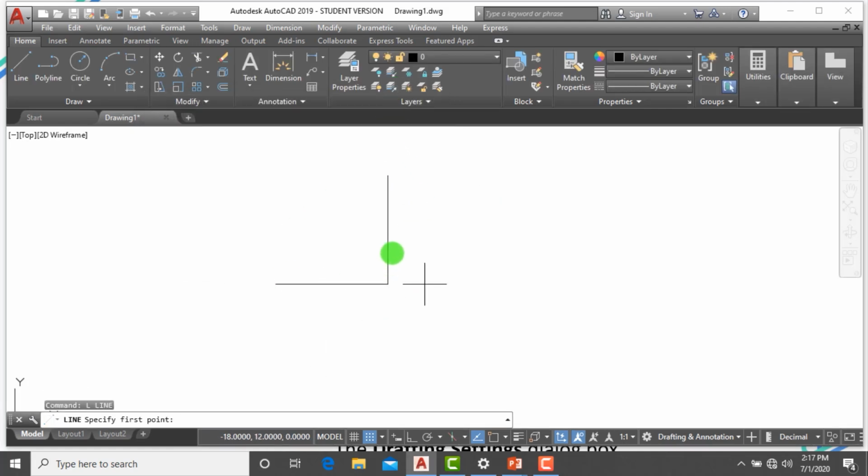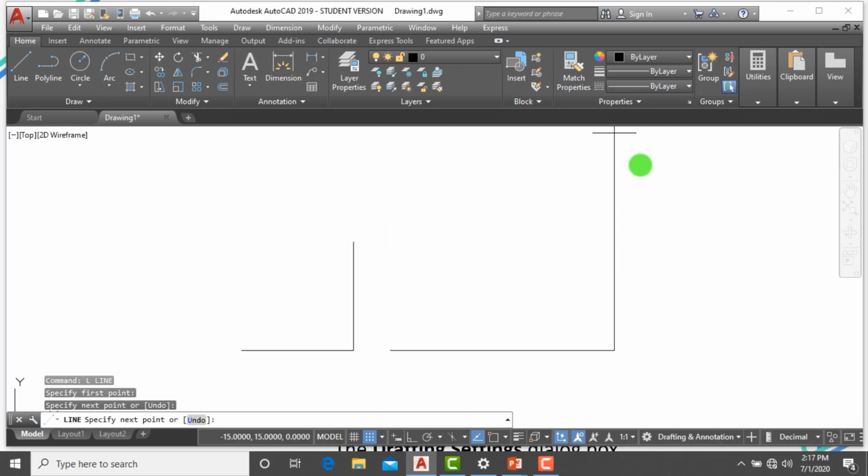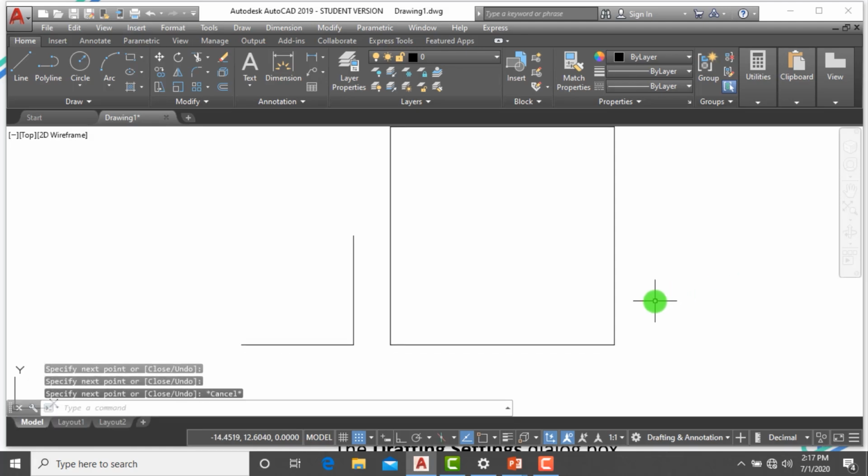Now here, once you click on it, the next snapping is basically if you move the cursor, it's in the 3 units. So then it is in the 3 units. So now you know that the cursor is snapping only at 3 units in X, Y, right? So a 3 by 3 square is created. So it's a very easy way to work.